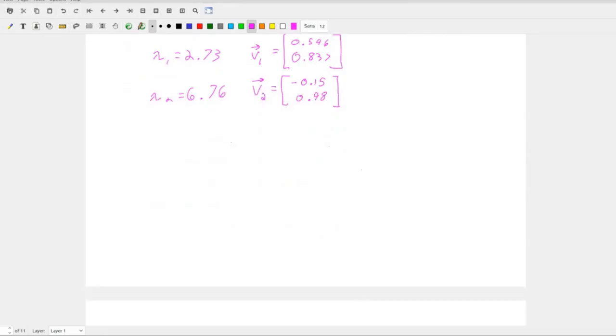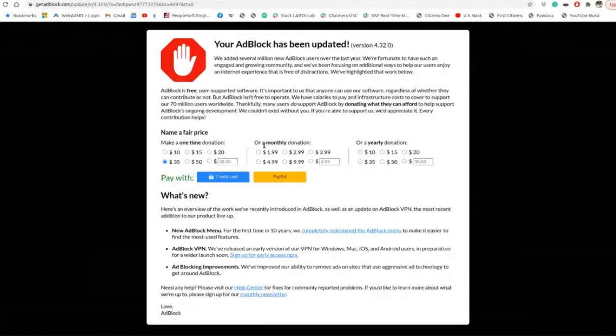Okay. Eigenvectors, eigenvalues to natural frequencies. Square root. Super simple, right? So omega 1 is equal to the square root of lambda 1, which is equal to 1.65. What are the units? Radians per second. All right. So because we use the generalized eigenvalue approach, how do our eigenvalues relate to our eigenvectors? Sorry, how do our eigenvectors relate to our mode shapes? Do we have to do the M to the negative 1/2, or is it just